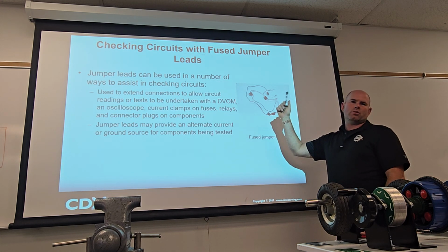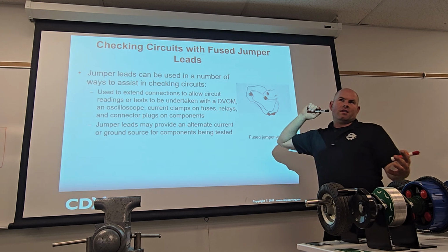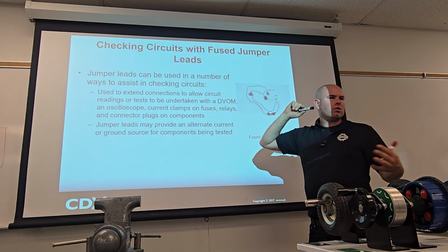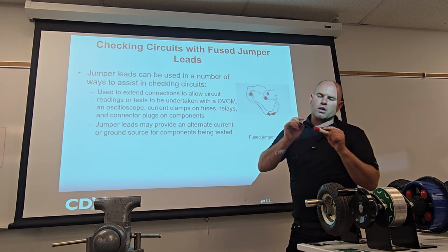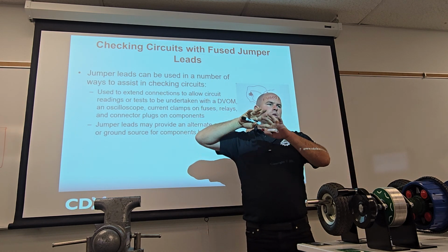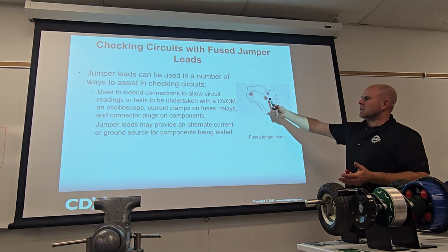And I would probably have it fused with a pretty low amp fuse. That way, once again, we're especially concerned about computer controlled circuits. When you're probing the wire outside of the computer, it's still connected to the inside of the computer with the small printed circuits. Remember electronics? Cool, so it's a good idea.